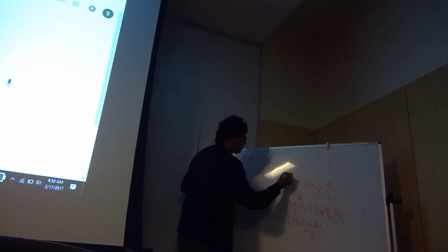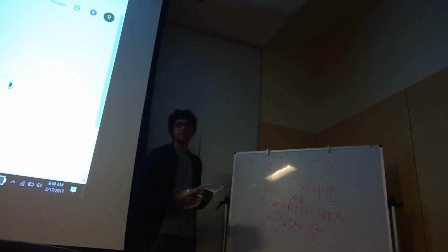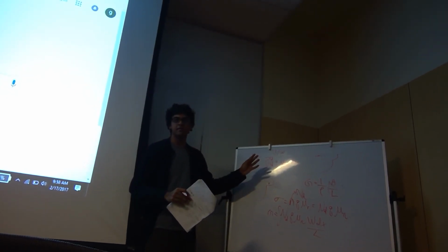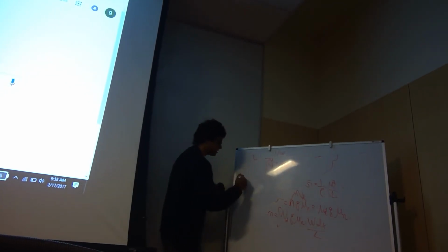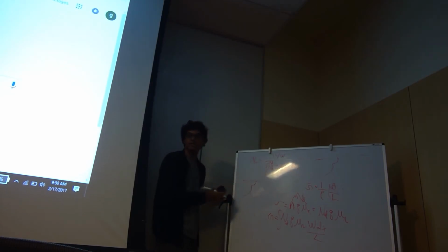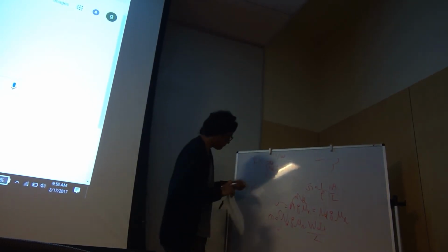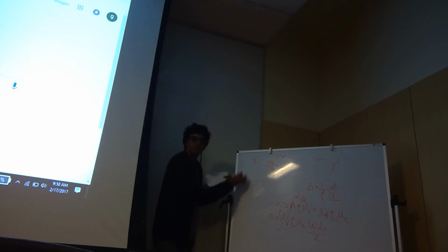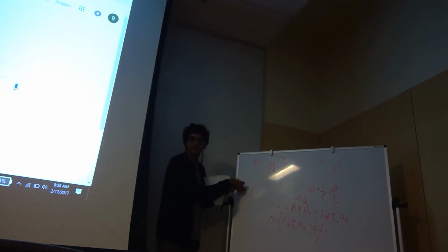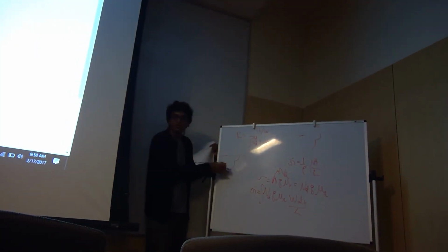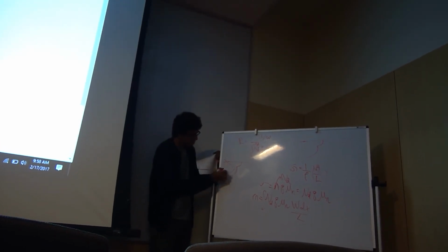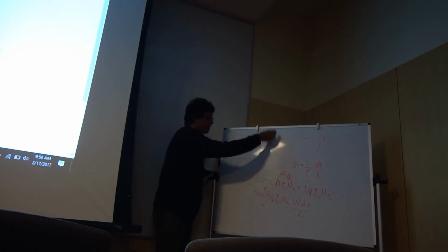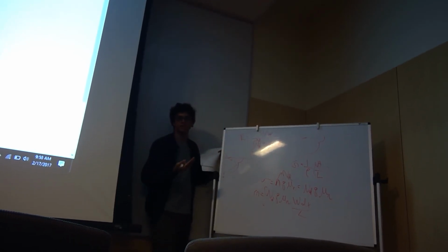Why is there an L over W term at the top? I took the reciprocal. So this is the formula for the resistance of any region like this. Now, in order to create this, you are actually implanting, so you have a concentration variation along this direction. This direction was the x direction. Say you have some Gaussian profile here. All you're doing here is integrating this profile, and the reciprocal of that profile times L over W is your resistance.